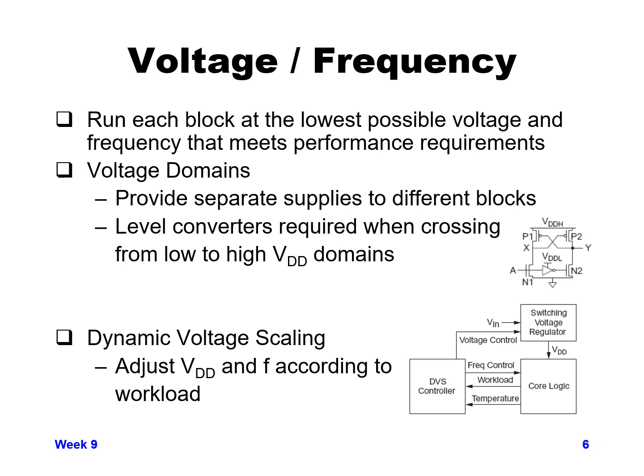So of course, you do get a double effect out of that, almost a cube law effect, because you're reducing voltage by a square function, then reducing frequency along with that, and so you can get a pretty dramatic reduction in power. Now, this can be definitely a benefit if you know that the block that you're running, or whatever function that you're running, doesn't need the frequency maybe that some other portion of your circuitry does.